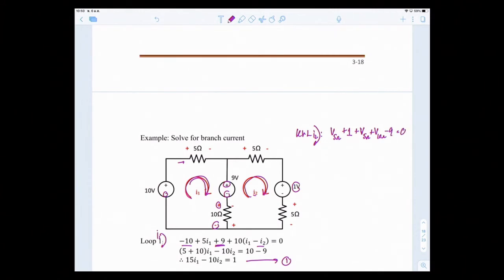Okay, the voltage drop across R1, the first one here, has I2 passing through it. So 5 I2 plus 1, plus this is also I2 passing through it, so 5 I2, plus 10 times what? I2 going, so we're now in the second mesh. According to I2, this is positive, this is negative.